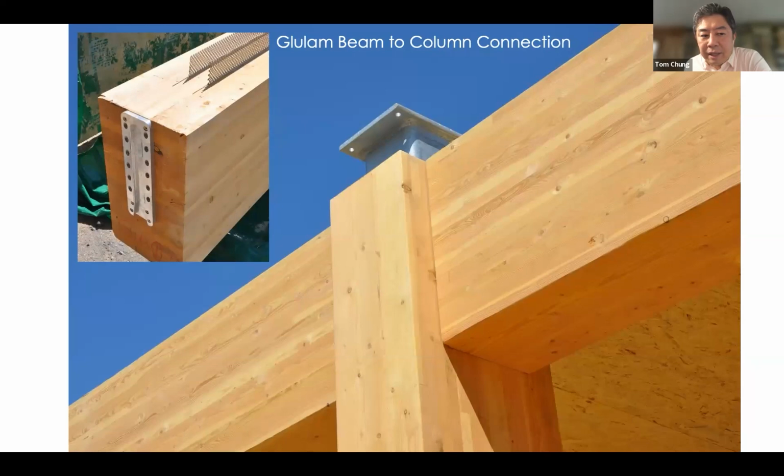It's just that it's hidden, and there are advantages here in that, as I've mentioned earlier, when exposed to fire, mass timber will char, and the inner area will be protected and maintain structural integrity. And it keeps this critical steel joint from being compromised in a fire by being protected by wood. It's kind of ironic, but given how wood behaves in a fire with charring versus how steel behaves when left exposed without fireproofing, it will melt and lose structural integrity. This becomes a very favorable condition that's advantageous and inherently fire resistant.